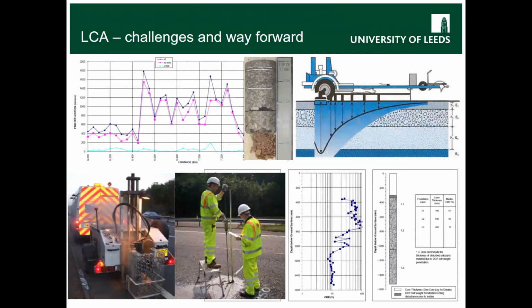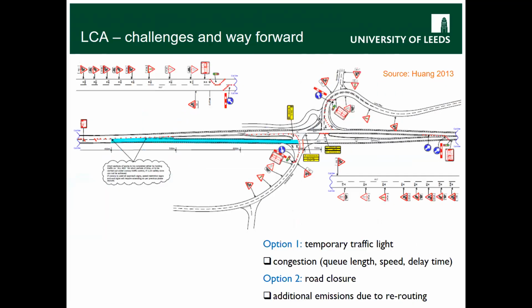We do the coring, where we can get the materials for lab testing, and we do the deflectometer and the penetrometer, so that we can get the strength of the foundation. So we really need these inputs from the people who work on the site. And another challenge is that for road maintenance, we almost always look at the lane closure and diversion. So we need the traffic management expertise.